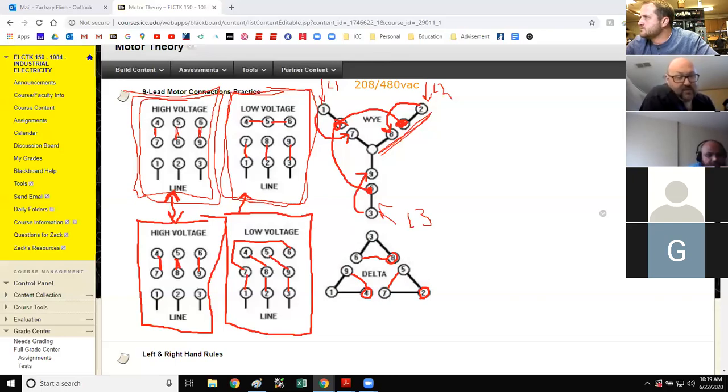But if you do that, does that mean that you have a high leg in that? High leg, what you're talking about, like the wild leg. Yeah, 230. Yeah, that's in a transformer. So that's where you center tap a delta winding and it gets all funky. I rarely see that. I've seen that one time in the field. Was that you that was telling me you saw it once? Yeah, Butch's Pizza. They run a high leg transformer to their trucks when they hook them up outside.